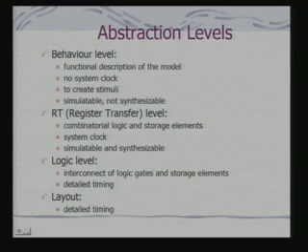If you think in terms of designing an FSM, what does designing an FSM mean? You identify the states, you identify the flip flops required for the realization of the states, and then you require the input signals, and you design the combinational circuit to provide the input signals that would cause the state transitions, as well as identify the output signals required for driving your external circuit.